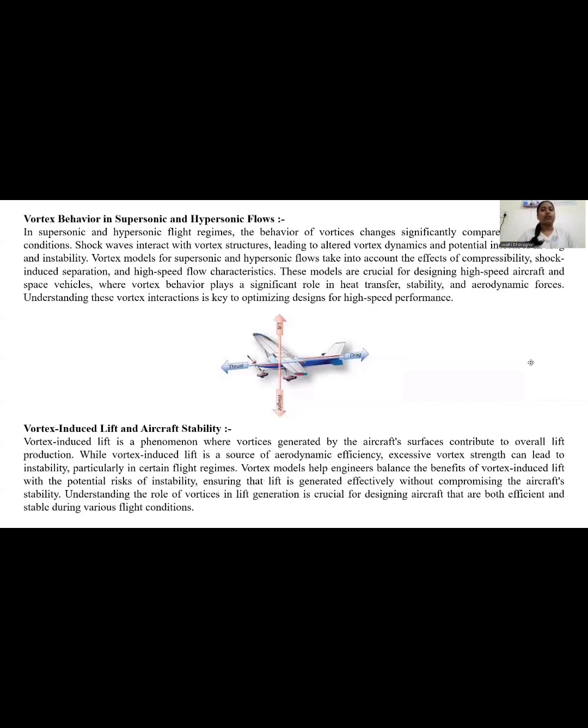Vortex behavior in supersonic and hypersonic flow. In supersonic and hypersonic flow regimes, the behavior of vortices changes significantly compared to subsonic conditions. Shock waves interact with vortex structures, leading to altered vortex dynamics and potential increases in drag and instability.